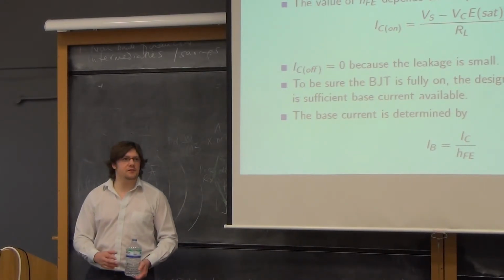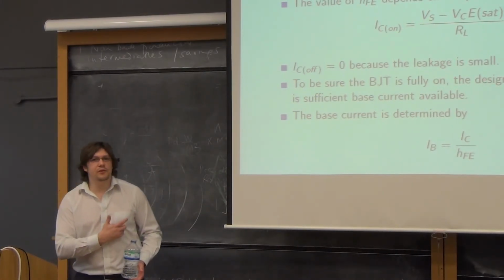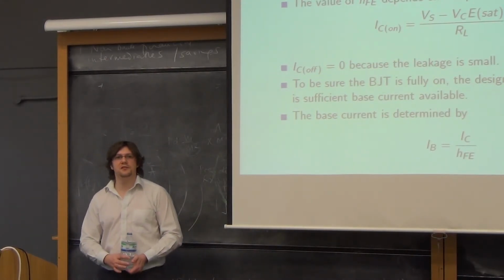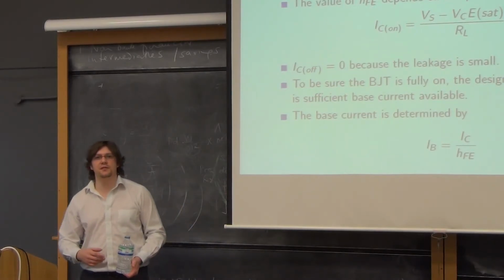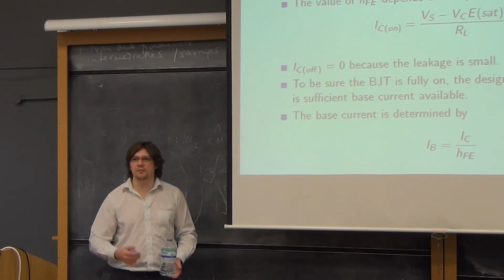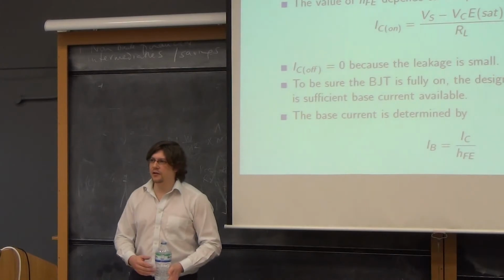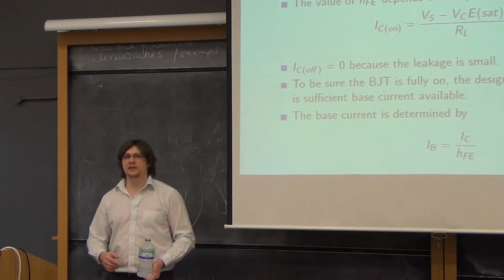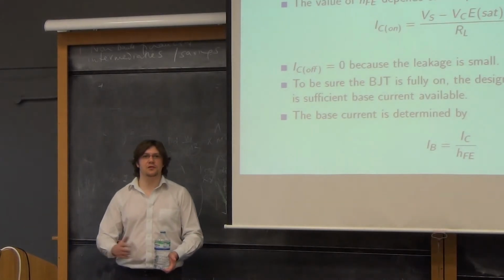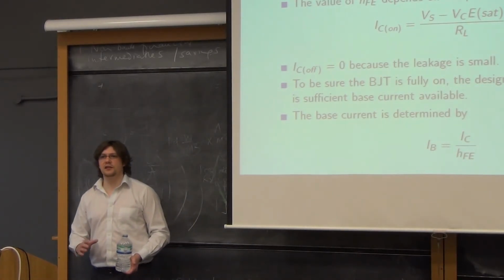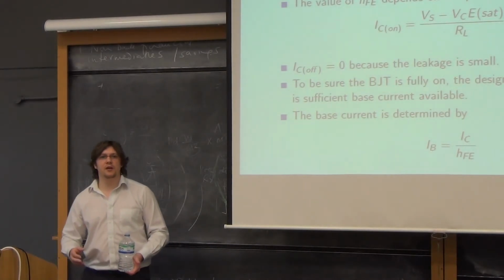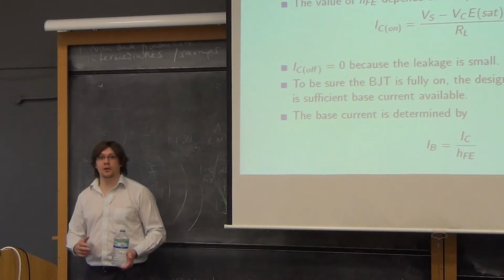In the sort of CMOS 1.3 volt multi-core, multi-gigahertz processor, the leakage is actually quite significant. Now you say, alright, I've got a picoamp and 100 billion transistors. Well, that means you could have a leakage current of almost an amp across all those transistors. So even though the leakage current is small when you worry about one transistor, if you're in some VLSI problem, you could have quite a big leakage current.